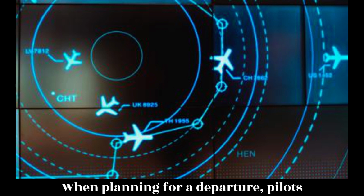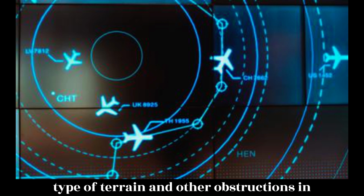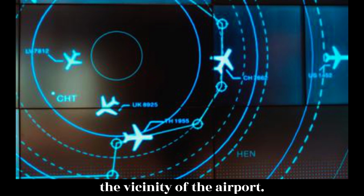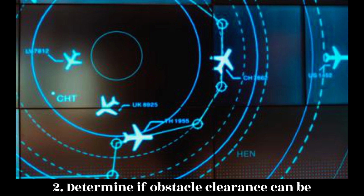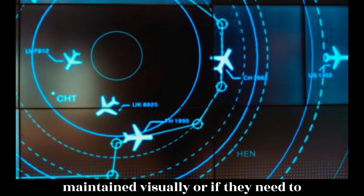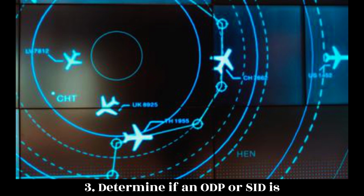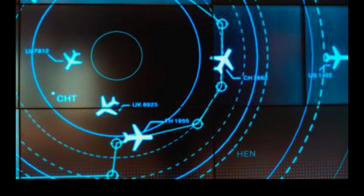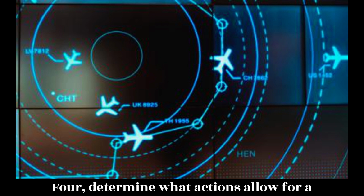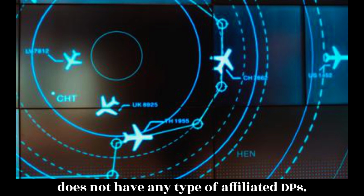When planning for a departure, pilots should 1. Consider the type of terrain and other obstructions in the vicinity of the airport. 2. Determine if obstacle clearance can be maintained visually, or if they need to make use of a DP. 3. Determine if an ODP or SID is available for the departure airport. 4. Determine what actions allow for a safe departure out of an airport that does not have any type of affiliated DPs.